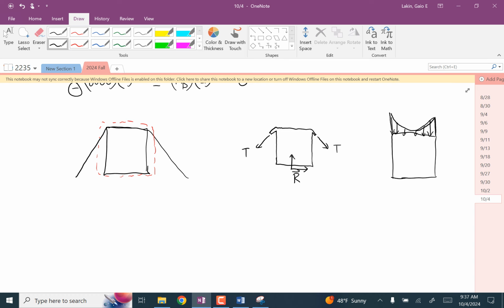Okay, so if you're just trying to figure out the tension in that cable, then you could do it like this middle picture, and that's the end of it. If you're trying to figure out how likely that is to damage this box, then you have to treat it like a deformable body. And then you can't use equipollent systems for that anymore. So then you'd have to calculate what are called internal loads and go from there to stresses and strains.